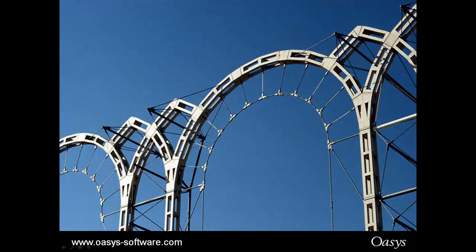Now, obviously, the ungrouted masonry is compression only, no tension capacity available, and you can use non-linear analysis to analyze these structures. We'll call that a flip-flop model, using just small compression-only elements, and tension-only elements to model the rods.